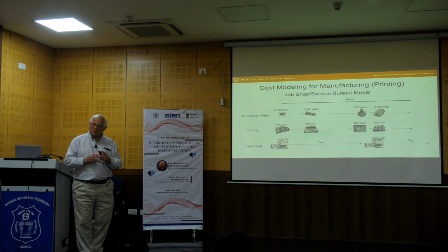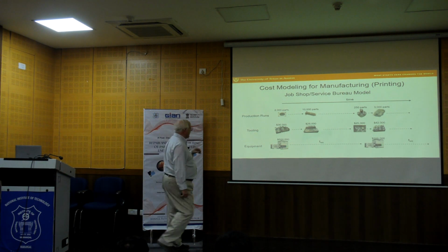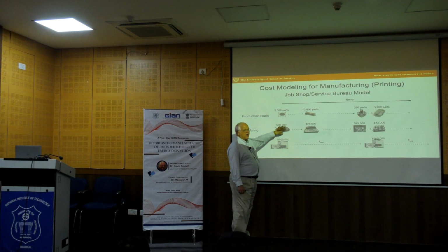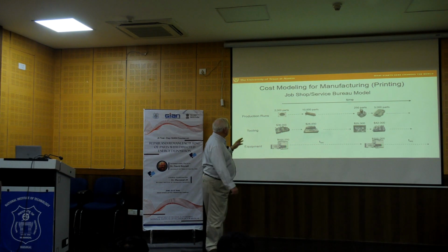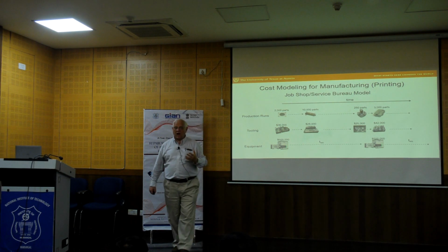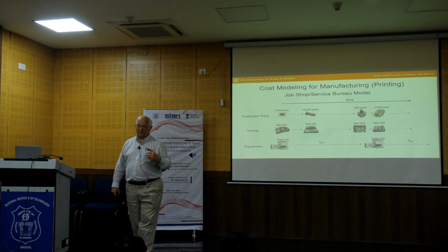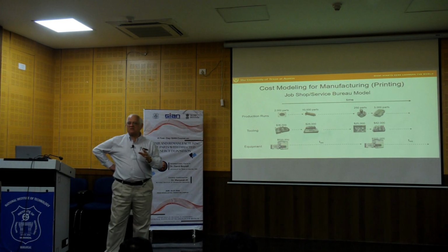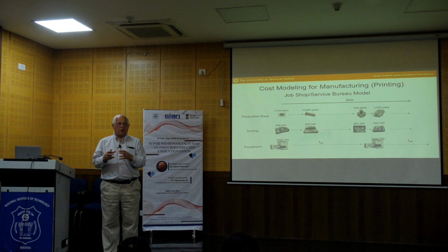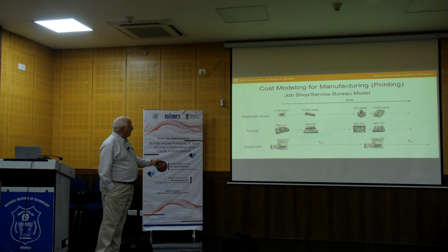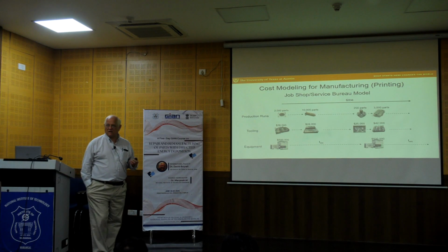And so the issue though is for this die set, if I have $36,000 on 2,000 parts, if I can do the math in my head, that's $18 per part. 36,000 divided by 2,000. That means that basically for every one of those 2,000 parts that I make, I have to assign $18 to that part plus some other stuff, but just to recover the tooling cost, right? So for this part, the tooling cost would be $18 per part.